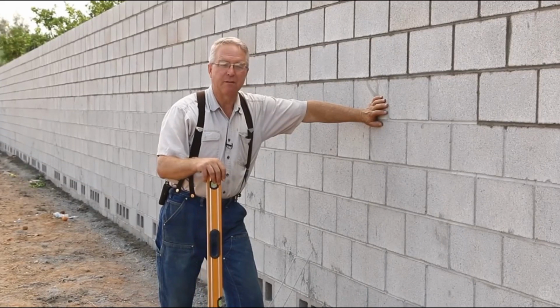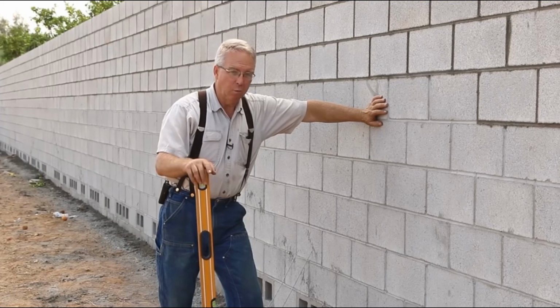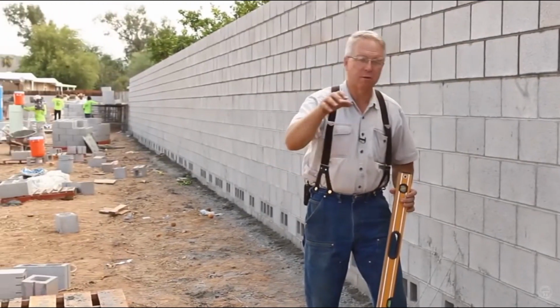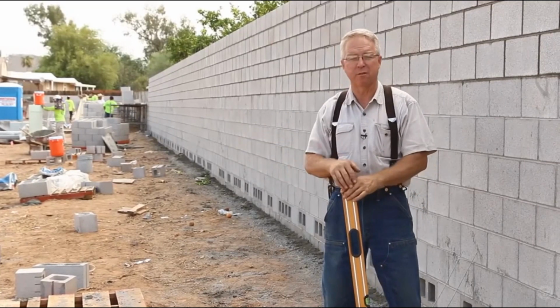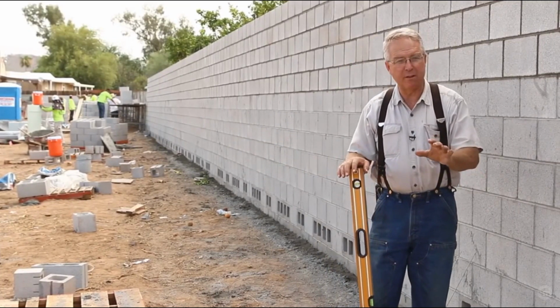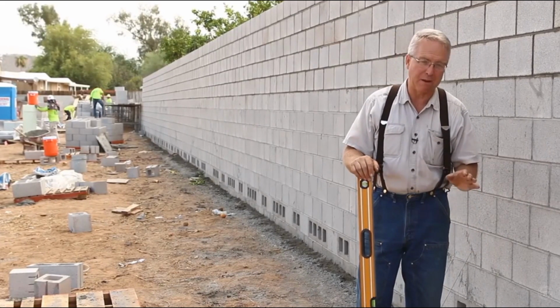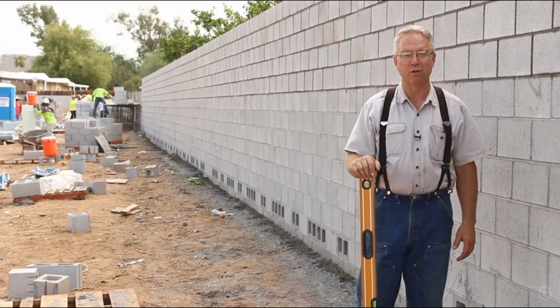So with the footing in place, cleaned up, with the block carefully staged in the right location, the right distance from the wall, and the right quantities and the right centers, with all of the supplies where they need to be so the work can start, now it's time to put down your starter course, your base course, and it's the hardest course in the whole wall.